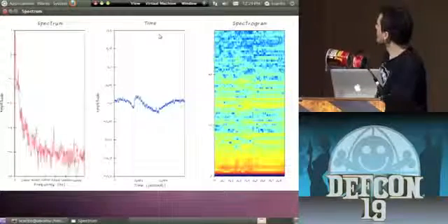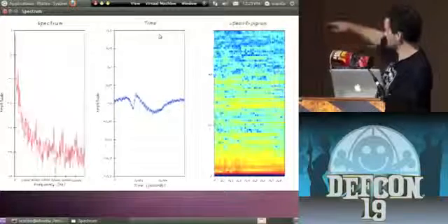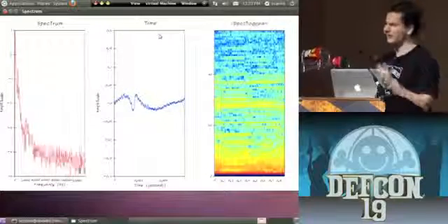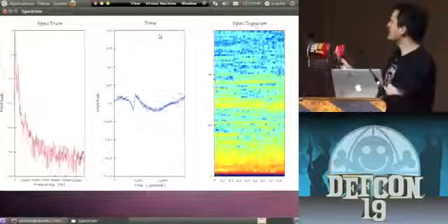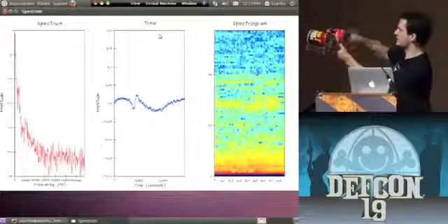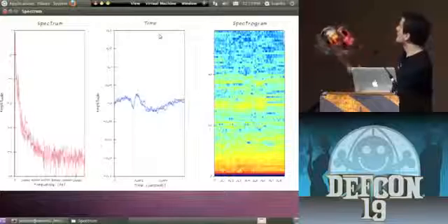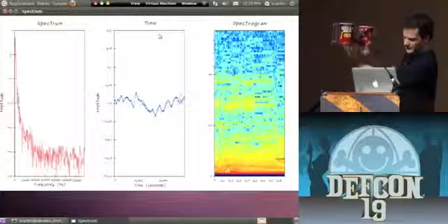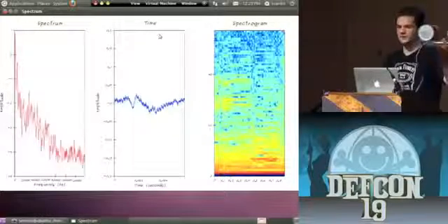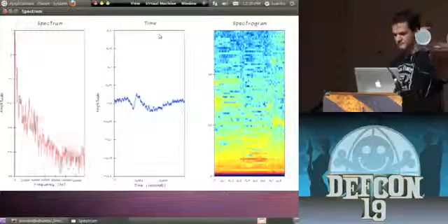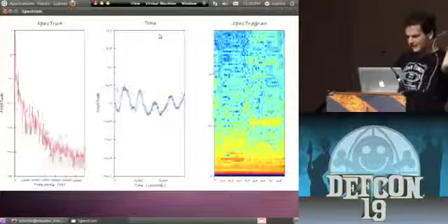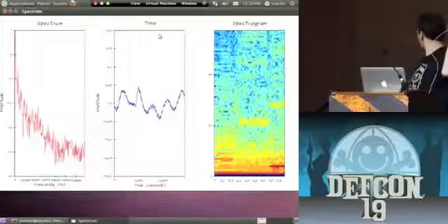It's kind of hard to see the scale here, but on that spectrogram view, those numbers are supposed to be the distance in meters to whatever you're looking at. So I guess if you've seen a fish finder before, it's basically the same interface. So what I can do is if I point it at the wall, I'm pretty sure that strong response at about 30 meters is probably about the distance of that, which sounds about right. If I point it up at the ceiling, it's going to drop down, and we see a very strong red line at about 8. It's about the correct distance, and we can just kind of scan it around. Yeah. So we get something at about 4, which is about right.